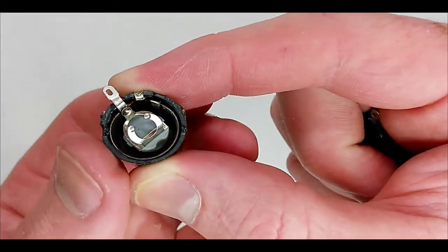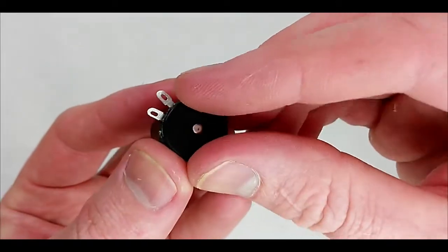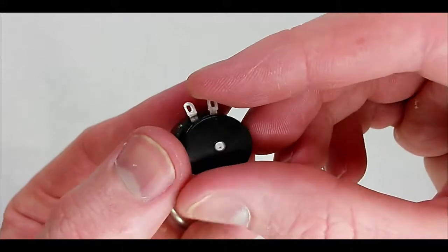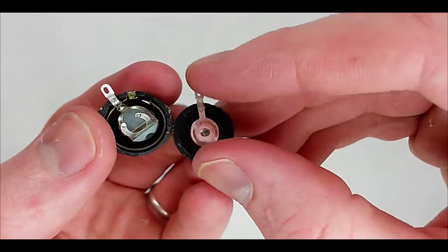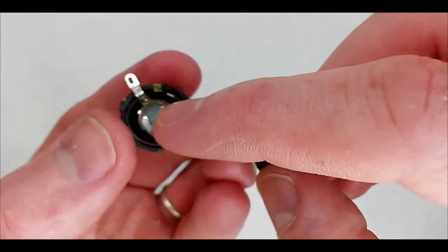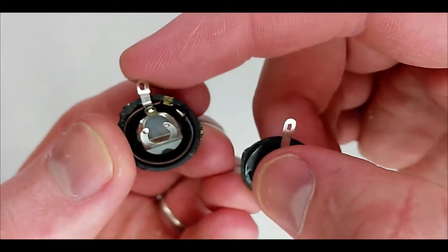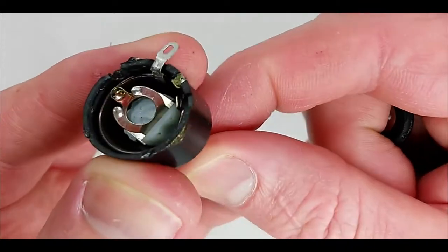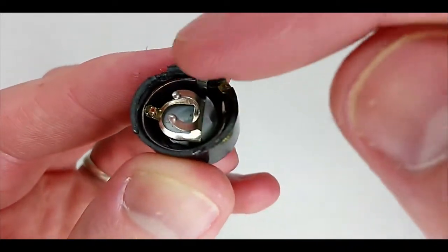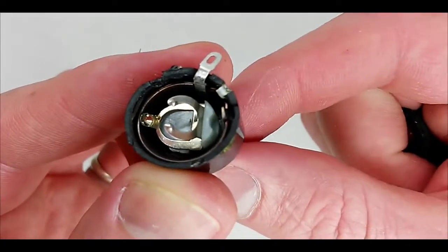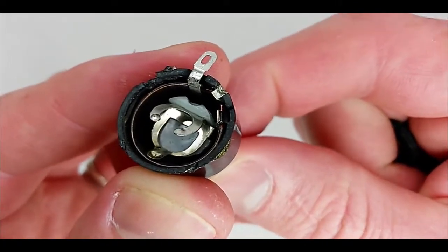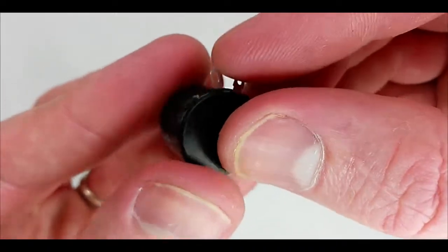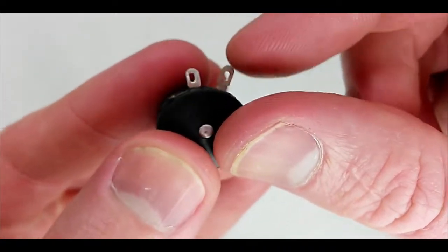So in that position, and if I was to put this back on top, if I was to measure the resistance between there and there, it would be 0 ohms. Because this bit of metal on here connects to this bit of metal on here, which is then directly connected to this bit of metal, 0 ohms. As I rotate it through, so this little round strip here is resistance wire, so the further that I rotate it this way, the more resistance there's going to be between this connection and this connection at the moment.